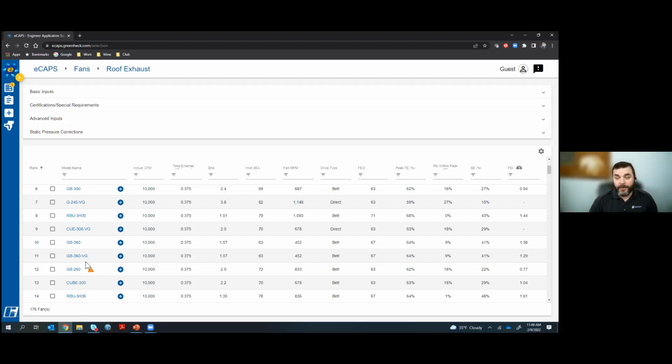So long story, not so short. It's not one for one. The higher the FEI, the higher the cost. But you will find that, like when we did our example, those three different sizes of the same fan, well, the biggest fan, the most expensive fan, was the one that had the higher FEI, but that was due to size and operating point.